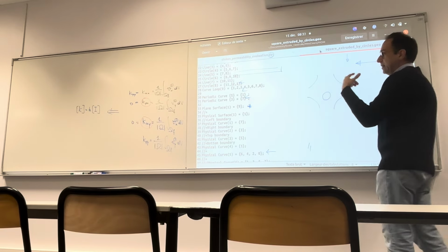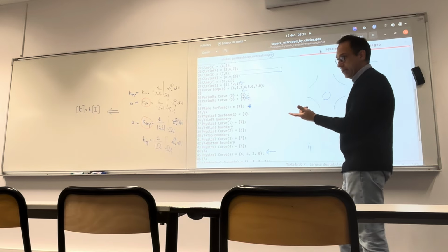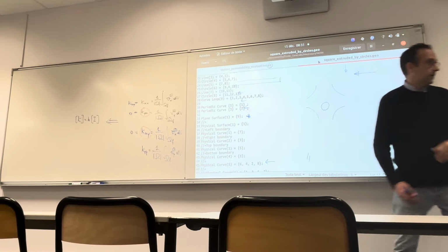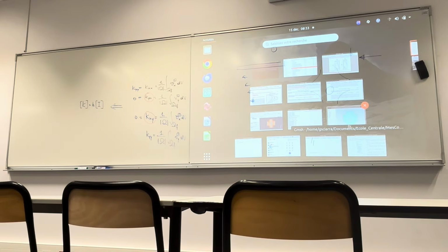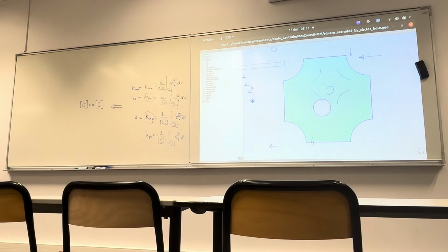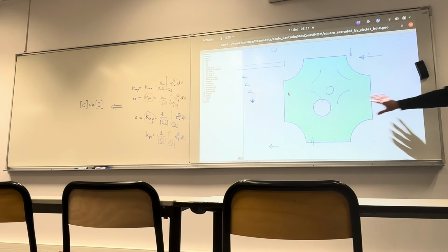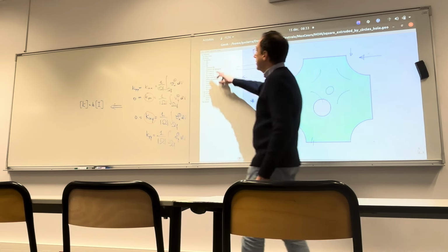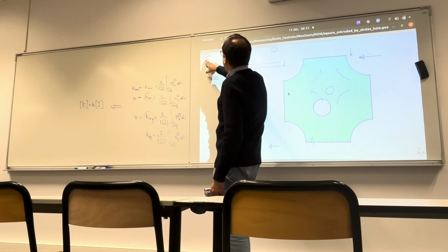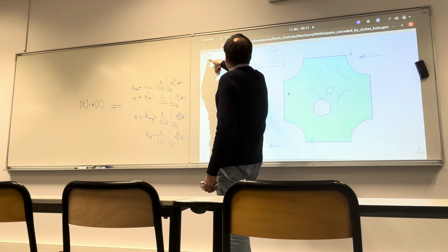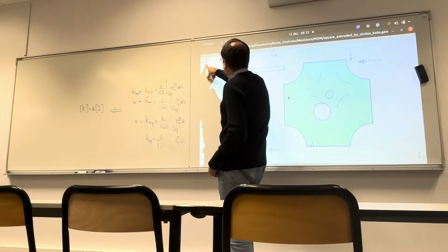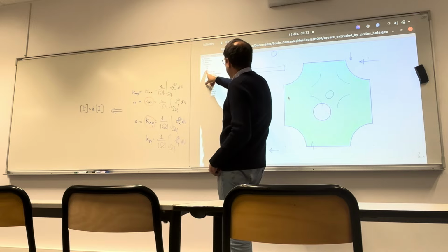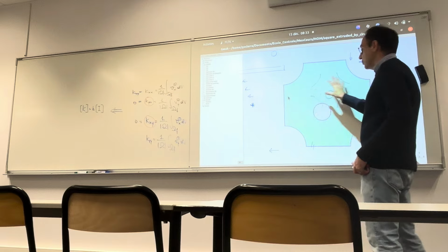You generate the new domain. Once you have it, you have to check that everything works correctly. You should be able to see something like that before. In fact, at the beginning you should see this without the mesh. Then you go into the GMSH software, you enter Mesh, you click on 2D and you generate the 2D mesh, which should be something like this.